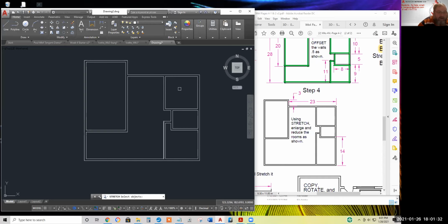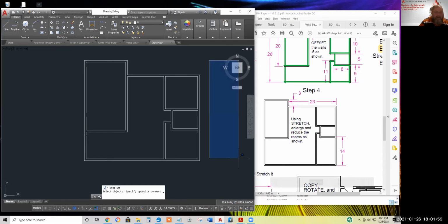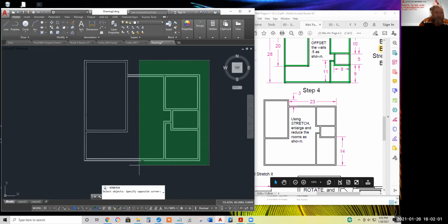Yeah, I think that will be these 3 rooms, including the outer wall of these 3 rooms. So like it or not, you've got to go out of your way to double check that you're selecting with a crossing window, and everything inside moves, and what's crossed by the crossing window turns into rubber bands. Okay. Click when you've got the crossing window enclosing and crossing what you want.